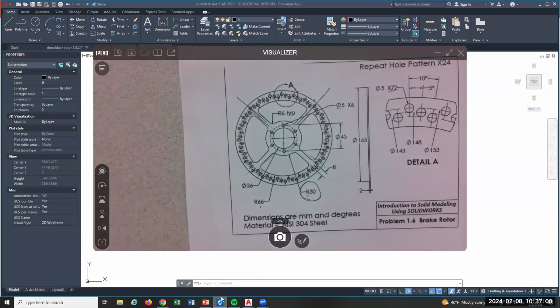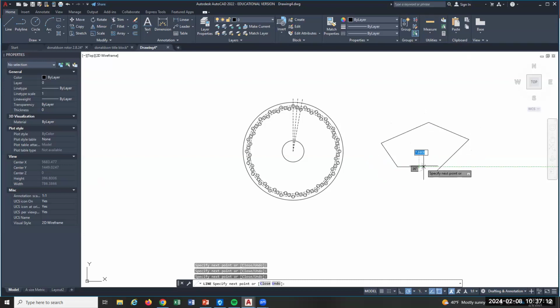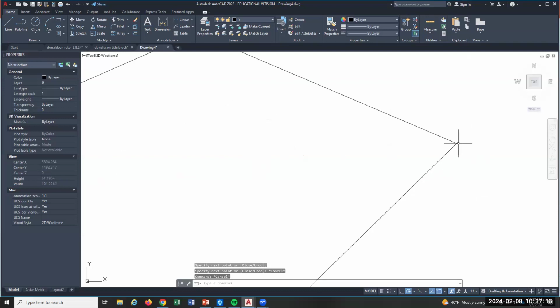Fillet rounds corners, right? So if you draw a shape, oh, I'm not gonna draw the arc, but that'll be an arc, and it comes down, and another arc, and that's really bad, right? But you can take these corners and you can round them up with fillet. So there's 2 things. There's fillet and chamfer. Chamfer makes a straight edge. Fillet makes a rounded edge.